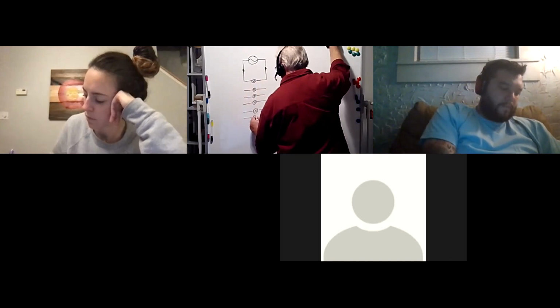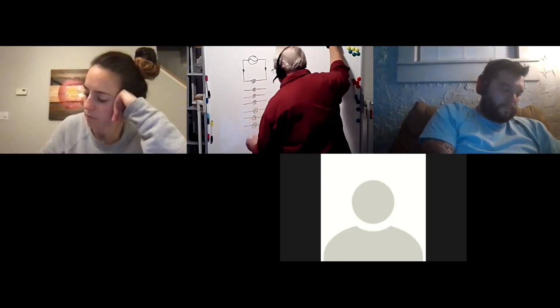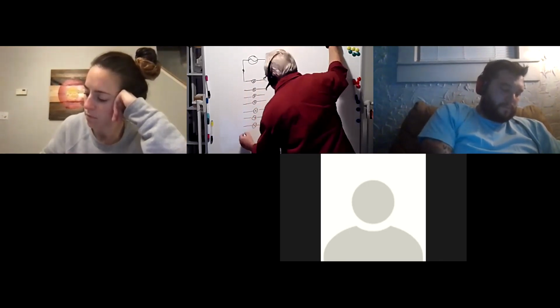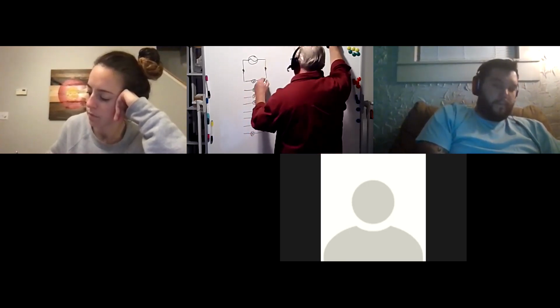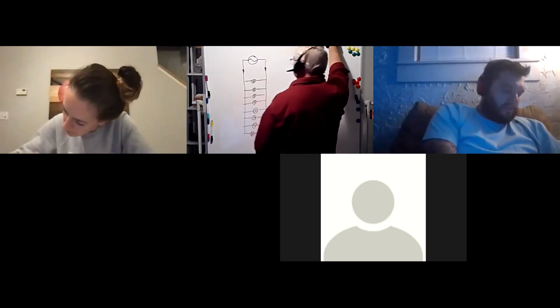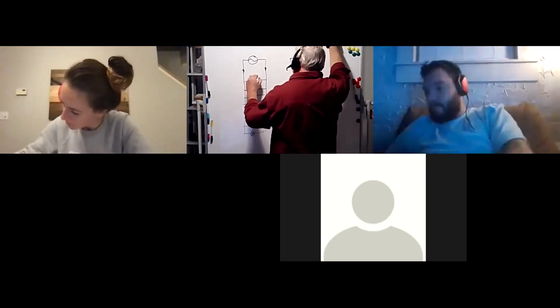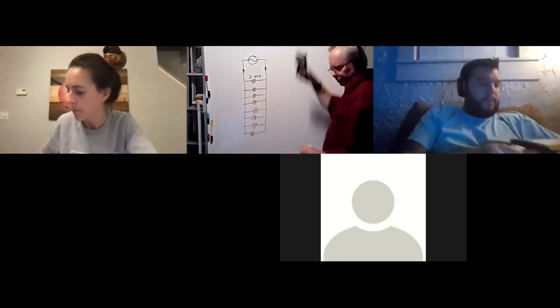Three more. You don't have to draw all that. I wanted to do this because since they're in parallel, the currents are going to add, and it makes more sense when we can see them. So these are all connected together. So 0.24 amps each.